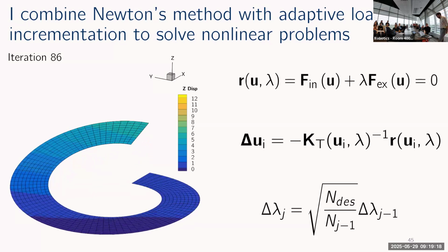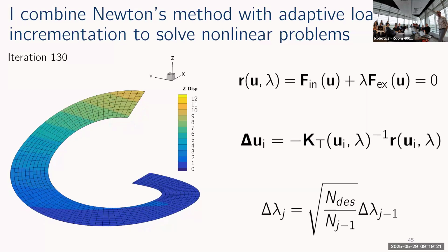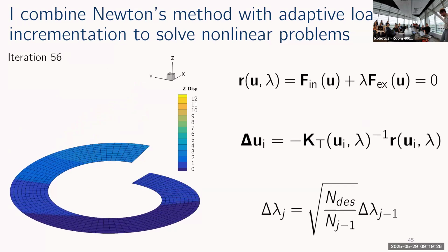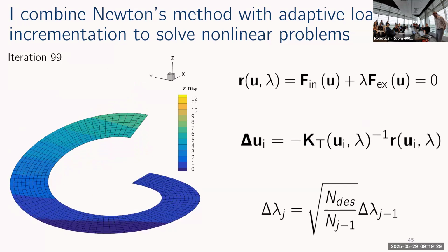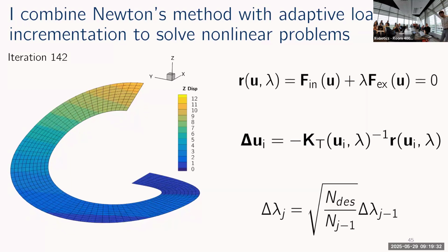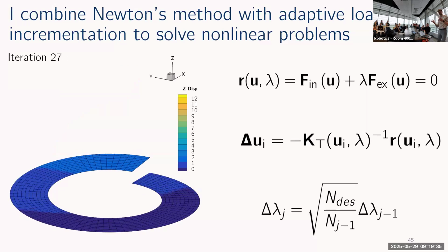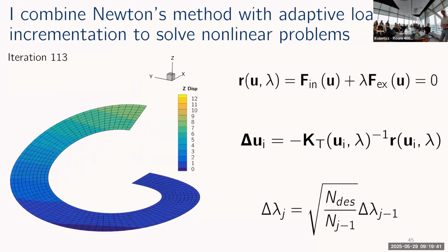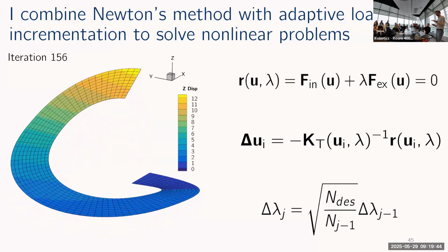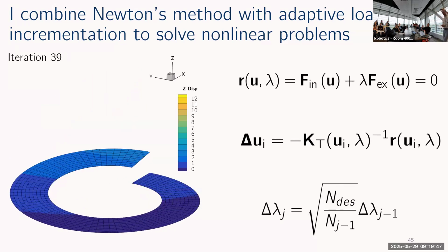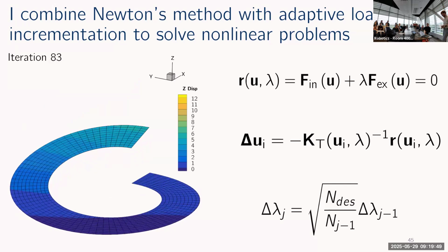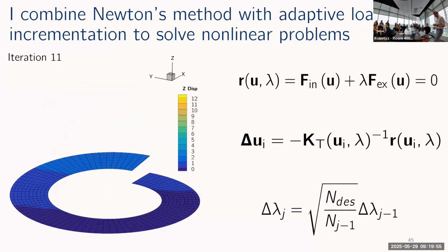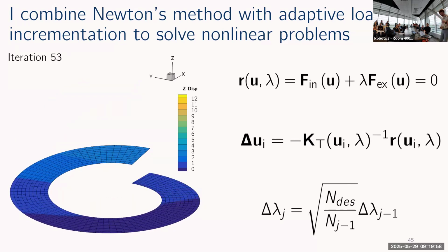And this solver combines Newton's method, which is a very well-known method for solving nonlinear systems of equations, with a load adaptation, load incrementation scheme, where instead of just applying the external loads fully in one go, what I do is I scale the external loads down, solve for the displacements under those scaled down loads, and then repeat the process, gradually increasing the loads till I get to the full magnitude. And I have a process in there for adapting the size of those load steps based on how hard it was to solve the last increment.